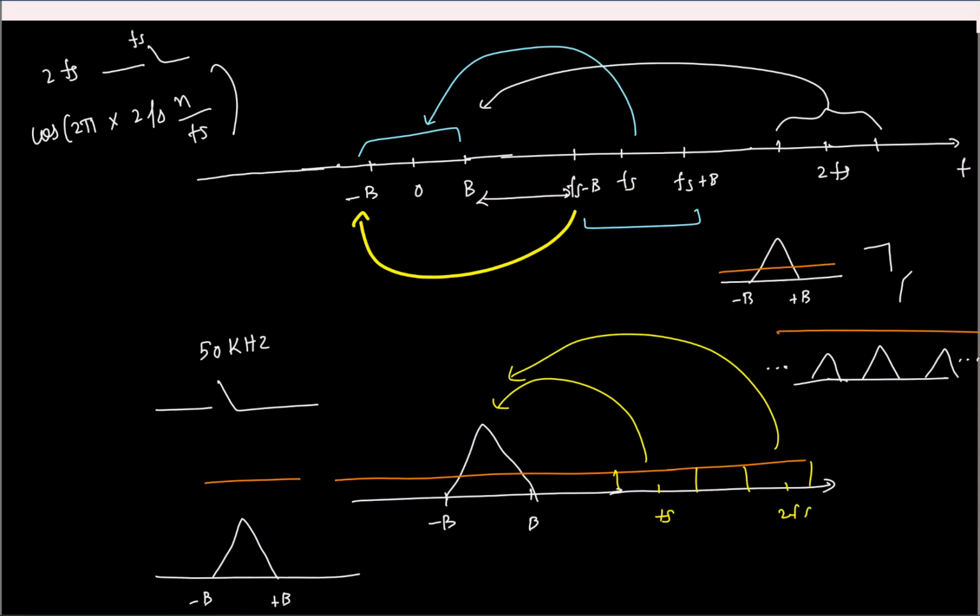Remember that after sampling, the spectrum is periodic in a discrete frequency range 0 to 2 pi, or minus pi to pi, or from minus Fs by 2 to plus Fs by 2 if you are looking at continuous time frequencies. Whatever spectrum you have is just going to repeat. So if you directly sample the signal, noise from around multiples of Fs will alias back to your required signal band and it will drown out your signal.